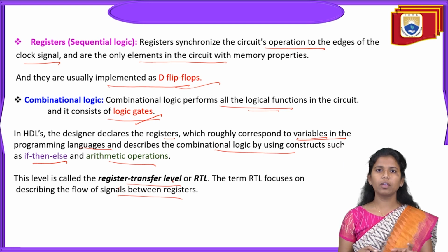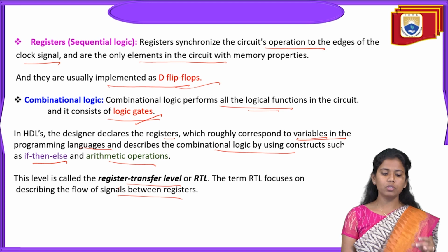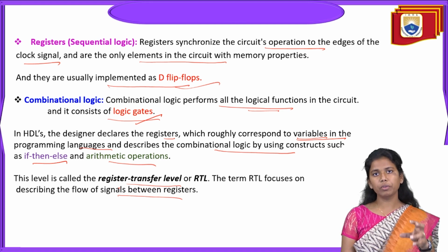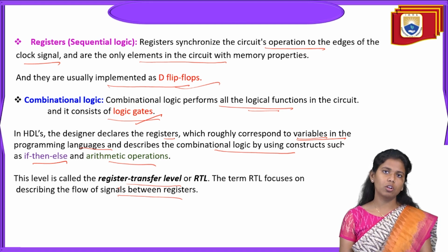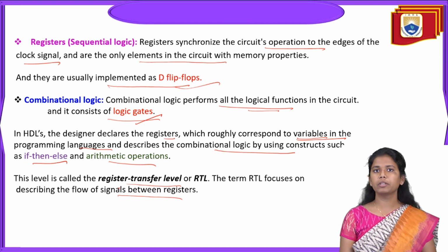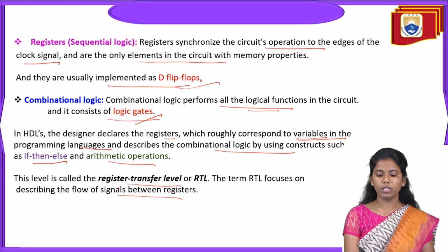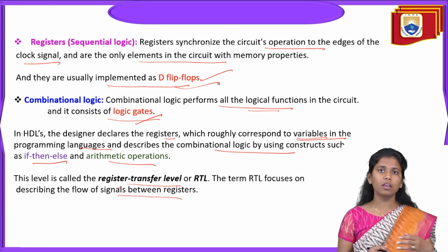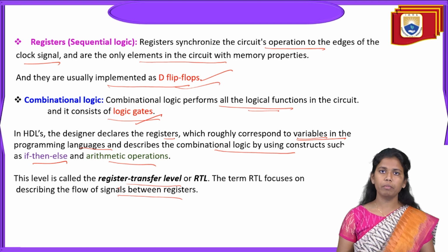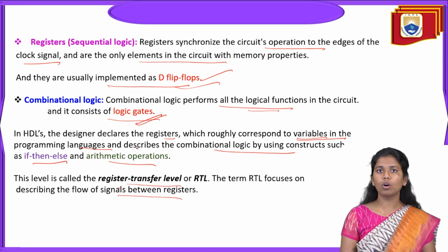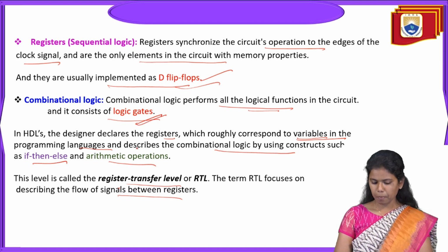So the flow of signals which contains some memory can be done by using the register logic, the sequential logic, or a combinational logic. If you are going as per the sequential logic, remember that the memory elements could be flip-flops. Basically, most of the time we make use of D flip-flops. If you are going as per the combinational logic, remember that your elements should go as per the logic gates.